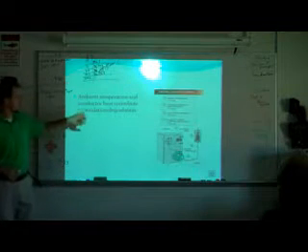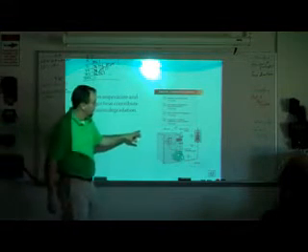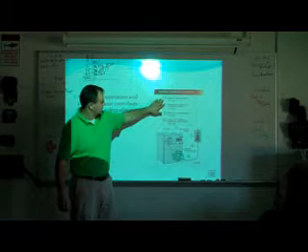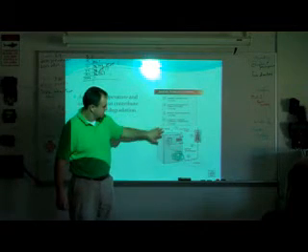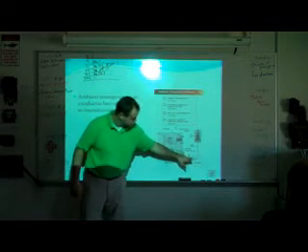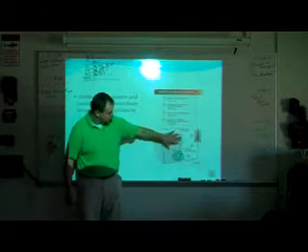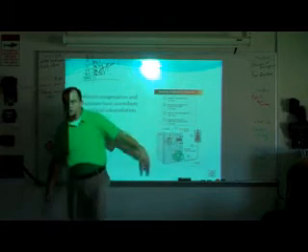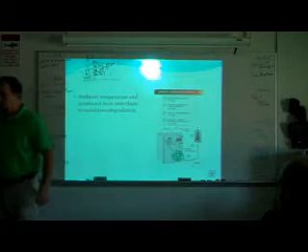So ambient temperature and conductor heat contribute. You have to take into account ambient temperature. So what we've got here is a boiler, an electrical panel, and here's our conduit. Anything that's on or around this boiler is going to be exposed to even higher temperatures.